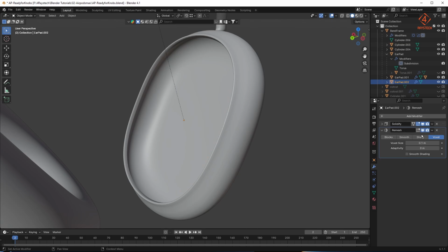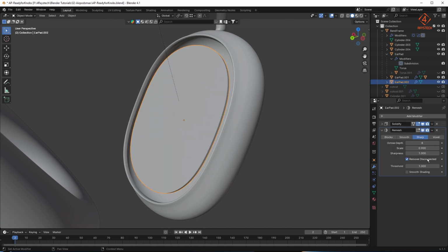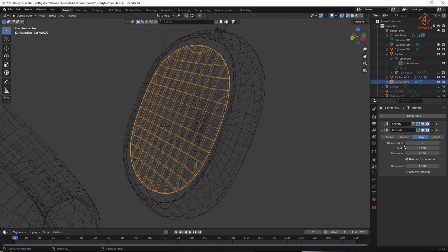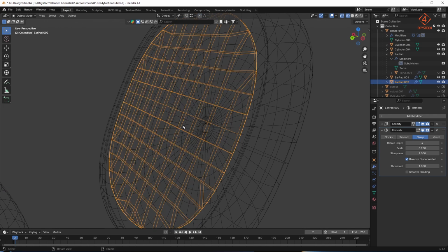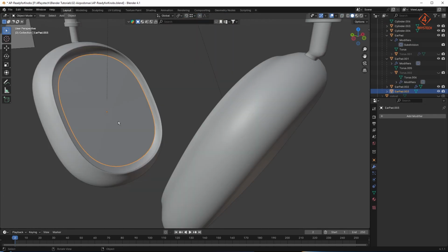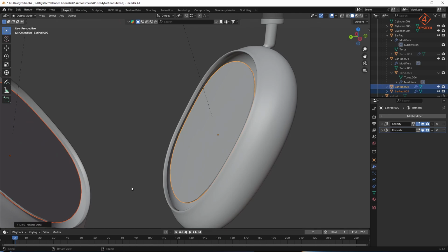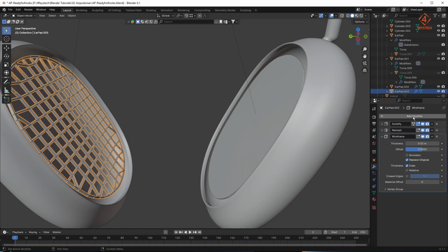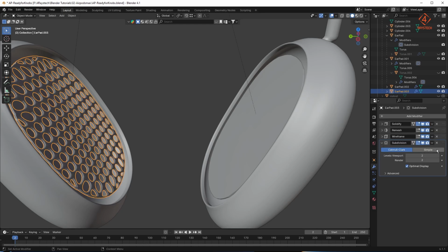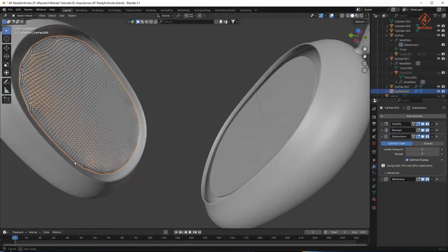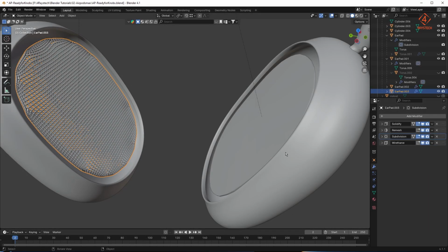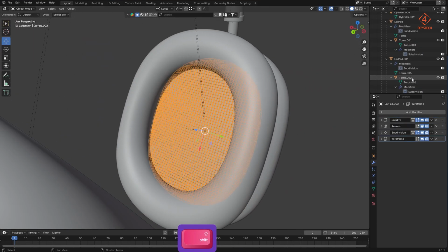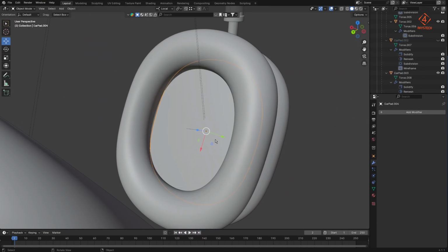I'll add a remesh node to create a bit more dense mesh inside it. So using the same wireframe, we can create more mesh. Remember, you can always copy modifiers by selecting one surface to another. Shift L and you can copy the modifiers. I'll add the wireframe and probably use a subdivider once again, but move it above to create a more dense mesh. Same thing on the other one. And I'll use one more copy of it underneath to fill out the space, so it's not see-through, as you can see in this one.